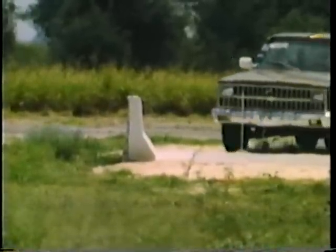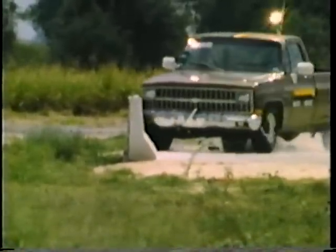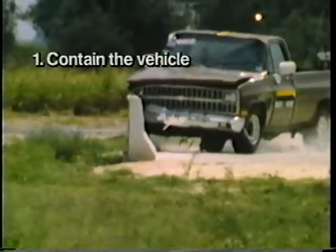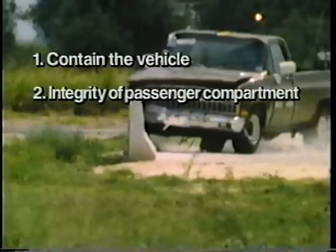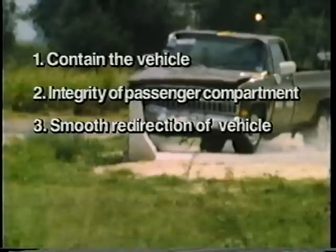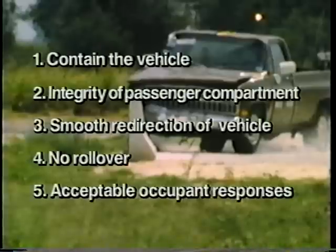The bridge railings in these tests must prevent the vehicle or its cargo from penetrating or going through the railing, prevent vehicle or barrier debris from entering the passenger compartment of the vehicle, smoothly redirect the vehicle away from the bridge rail without causing it to roll over, and ensure that the occupant's impact velocity with the vehicle interior is below the specified values.